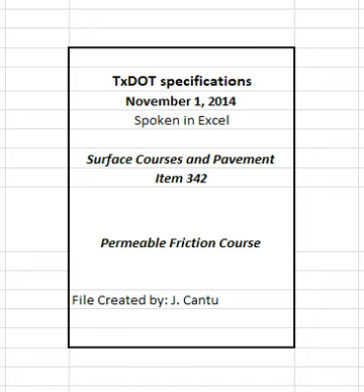Maintain the inline measuring device when AR binder is specified to verify the AR binder viscosity between 2500 and 4000 centipoise at 350 degrees Fahrenheit unless otherwise approved. Record AR binder viscosity at least once per hour and provide the engineer with a daily summary unless otherwise directed.